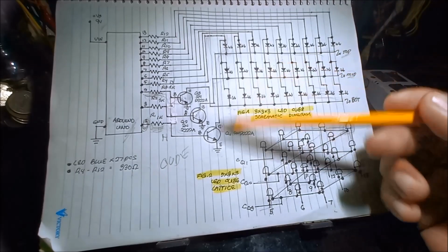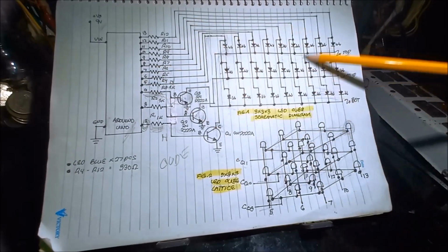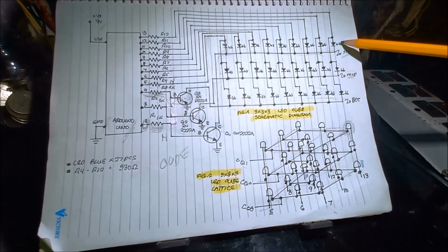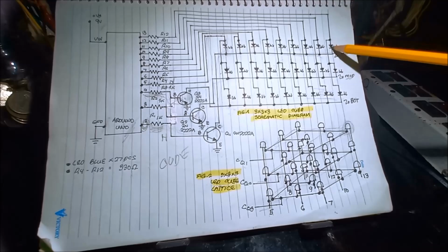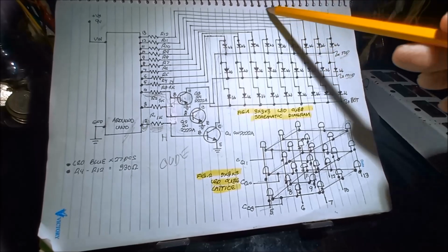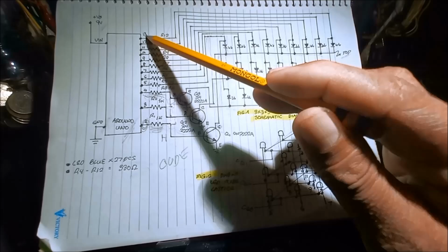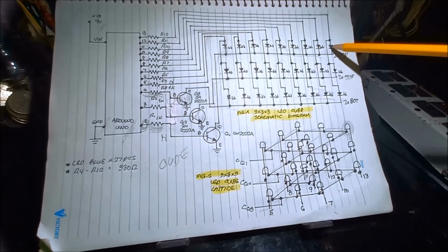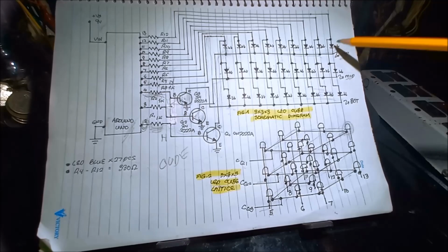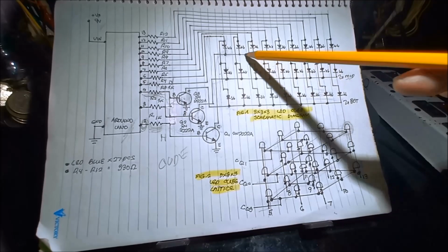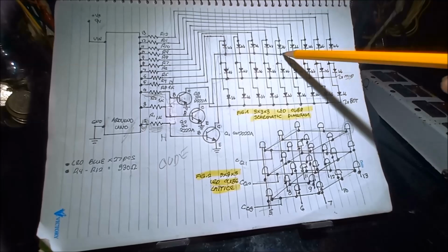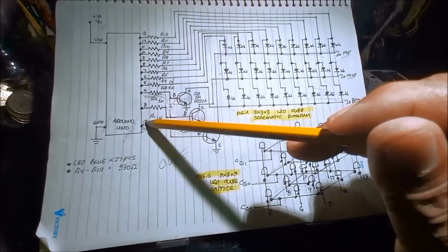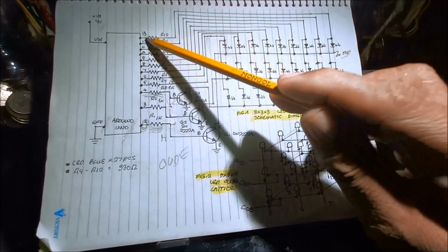And these are the construction of our project. If you're planning to turn on this LED, you need to set this pin number 13 high, and also since we're planning to turn on this LED, set this line high by turning on this transistor. So 2 and 13.